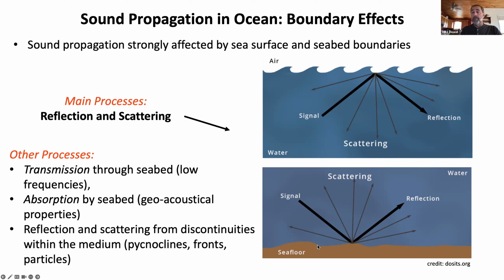Okay, next element. So we've talked about how the sound gets from the killer whale to the hydrophone and some of the things that people have to think about. What do hydrophones do? They're basically capturing the sound signal at the location that they're deployed. They typically measure acoustic pressure in micropascals, and you can see that the typical numbers for acoustic pressure are much, much smaller than the pressure that you see in the ocean, hence the ability to use these linear wave equations.